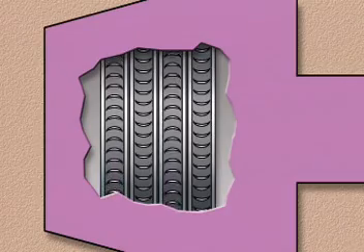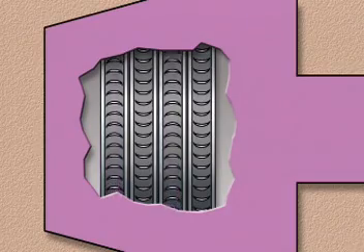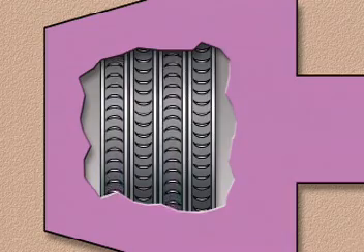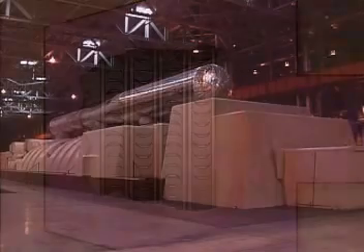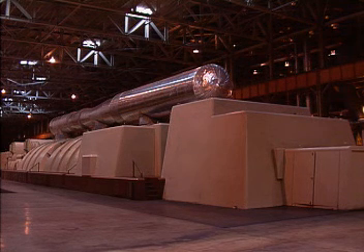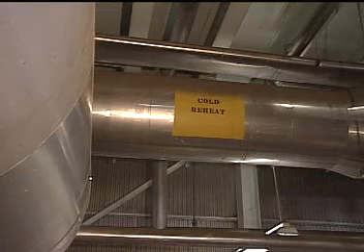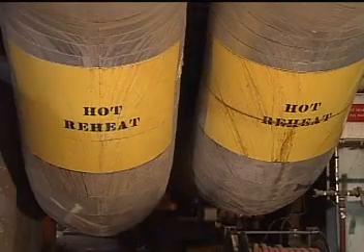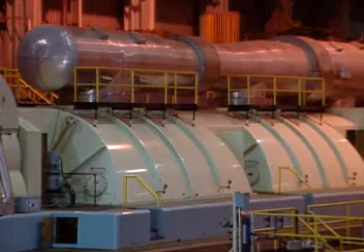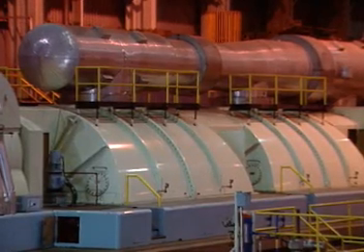When the main steam flows through the high-pressure section of a turbine, a lot of the steam's energy is used to rotate the blades that are attached to the turbine rotor. To increase overall plant efficiency, many plants direct steam that has flowed through and been exhausted from the high-pressure section of the turbine into a reheat steam system. This steam system then increases the energy of the steam and returns the reheated steam for use in the intermediate pressure section of the turbine.